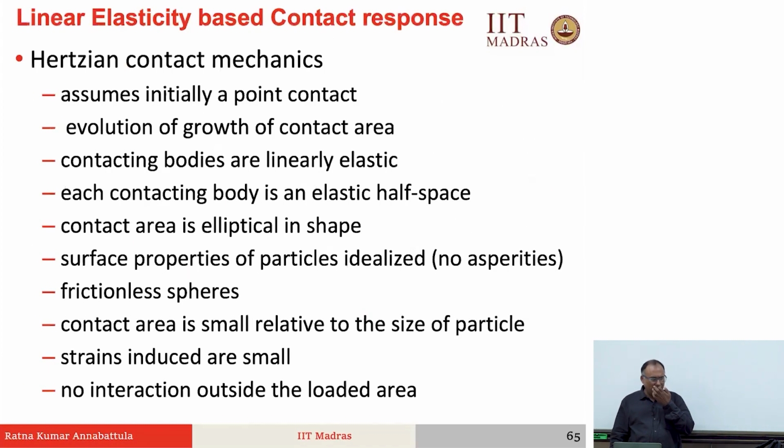So now linear elasticity based contact response. One of the contact models is what we call the Hertz-Mindlin contact model, or Hertzian, which is essentially based on Hertzian contact mechanics, which basically assumes both the contacting particles are linear elastic materials. There is no plasticity whatsoever. So it assumes initially a point contact before anything happens. First the particles will have a point contact and slowly with the application of the force, the contact area grows. So there is evolution of growth of the contact area, but during the entire period, the contacting bodies are still linear elastic